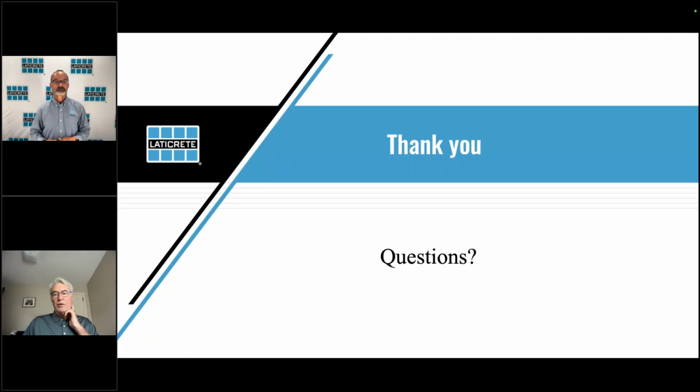Okay, so here's one about compact gravel. Can you put the base on a 1/4 inch minus compacted gravel? So, we've all walked at city parks where that 1/4 minus is hard as concrete. It's going to be situational. I've walked on that type of 1/4 minus, and then I've walked on 1/4 minus that's not compacted very well, and I'd be worried about settling. So I'm going to just say yes, as long as you're confident in how compacted that gravel is. Man, like I said, for 97 cents, you can get yourself a cheap little paver at Lowe's or Home Depot or something and throw underneath of it if you wanted to give it a little extra support.